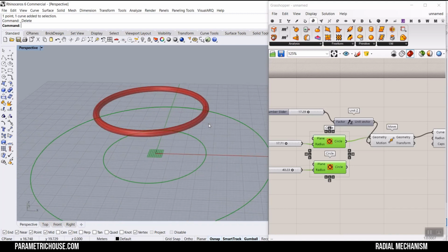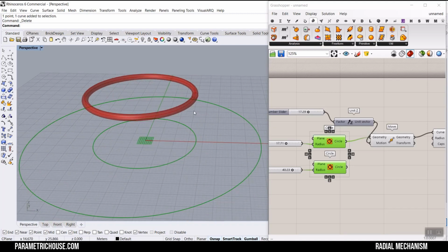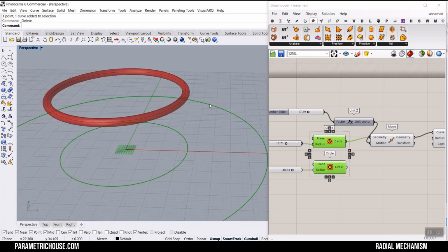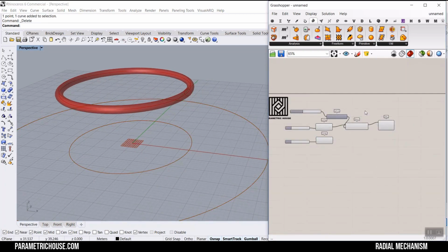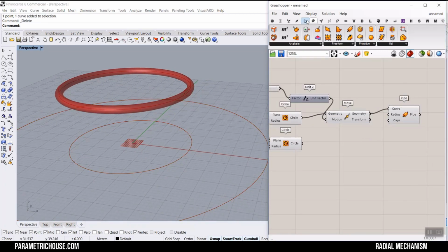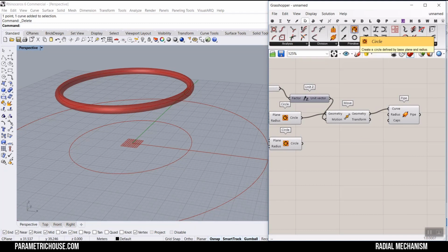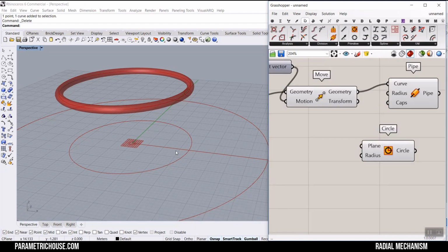Play a little bit with static parameters, because we're going to go to Grasshopper and use dynamic parameters, because they are going to change, right? So now we know the solution. We have to make that in Grasshopper. Okay, let's go and make a curve and a circle again. We have to give this an XZ plane. That means an XZ plane for the circle. So I'm going to say XZ plane.